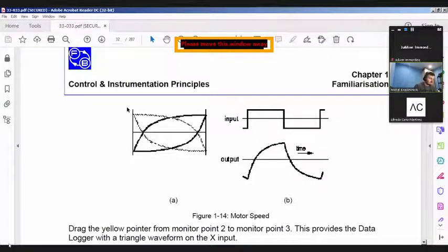But I still noticed that even though we used the maximum amount of derivative gain, and we had proportional gain and integral gain also maxed, I still could see that there was an overshoot. There was a triangular wave, and there still was an overshoot over the transient, and then it would level out nicely. But there was still a little overshoot.